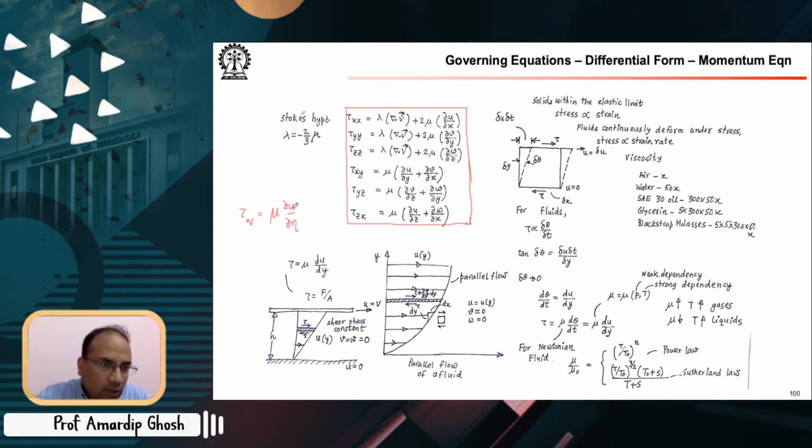So do not think of it as UVW; you can think of it as if your x-axis is along the wall at that point. Then the shear stress at the wall is equal to mu times the gradient of velocity normal to the wall, evaluated at the wall.